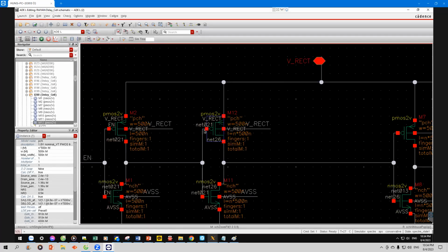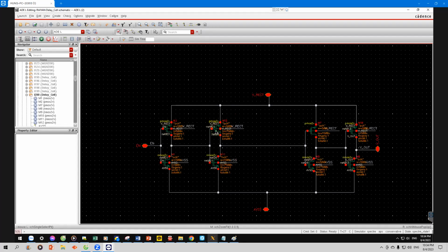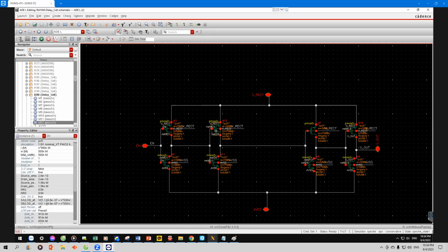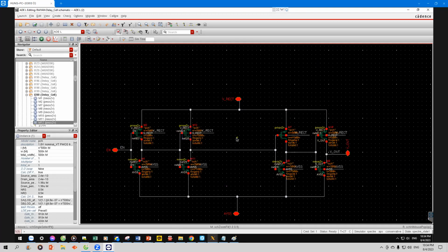Actually, in the layout, you cannot put N and M for MOSFET. In the layout, you have to make each a real number. That is a mistake that I missed this morning. So then I will just use 5 because n is equal to 20. Later, in here it should be 25 multiplied by 500. So you should put the real number here to do the layout, right?